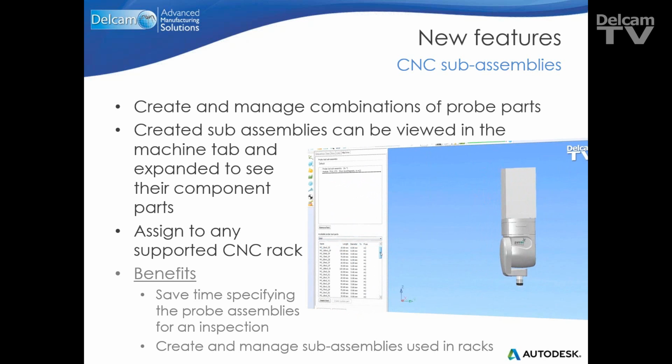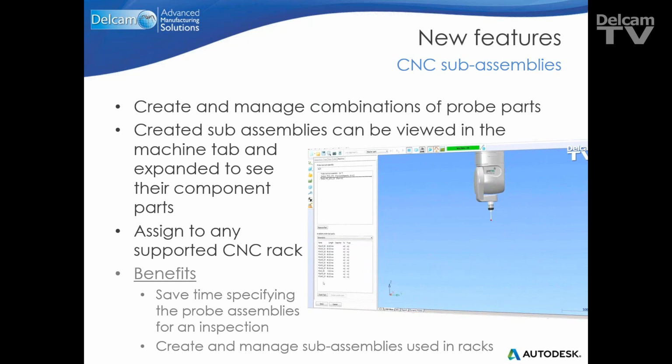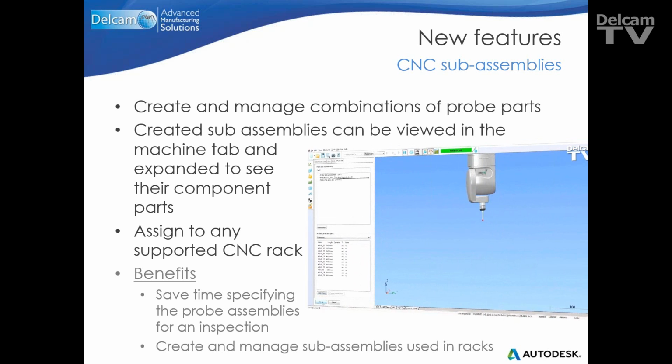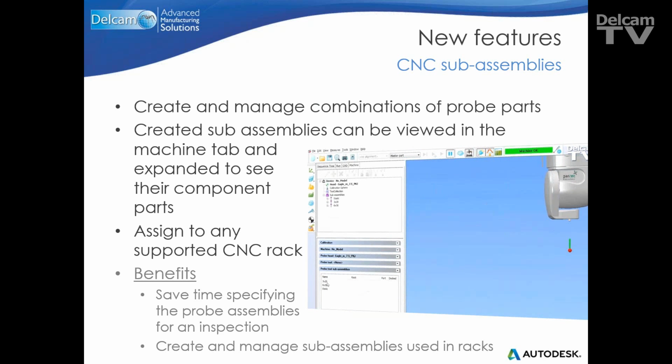Okay, the probe tool naming convention is paramount, but it's always given flexibility by being determined by the user. Now, you should also note that to eliminate confusion when you're building these sub-assemblies up, you should give it a naming convention which includes possible names like the module type, the styli length, and probe diameter, which are all very useful for aiding identification.